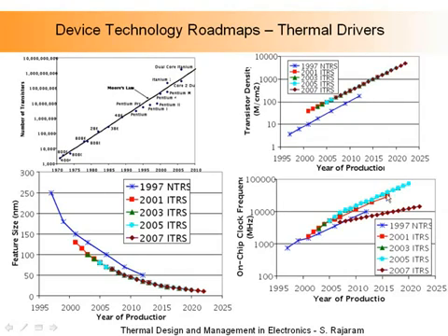And you're very familiar with laptops and PCs, where you buy a device today for 2 gigahertz, in 3 months it's 2.5 gigahertz, etc. The higher the frequency, the higher the power dissipation. So you combine the number of transistors and the higher frequencies, the product of the two means an ever-increasing heat dissipation. And this is what is driving those devices.